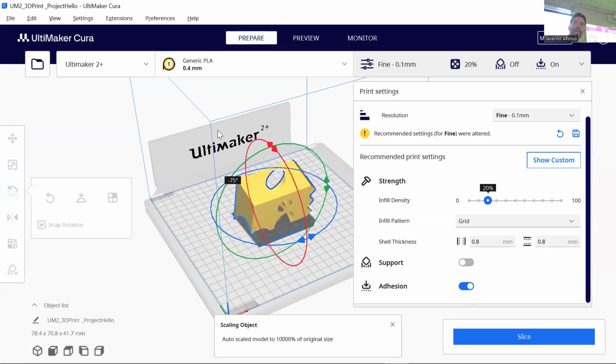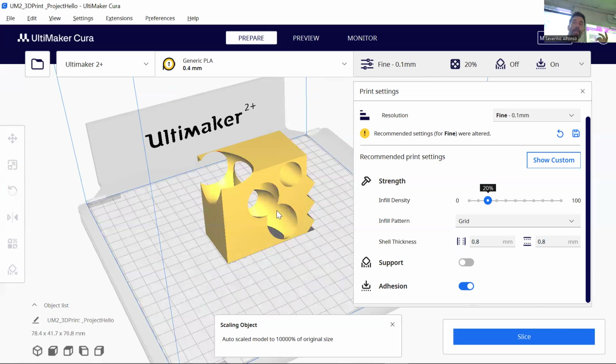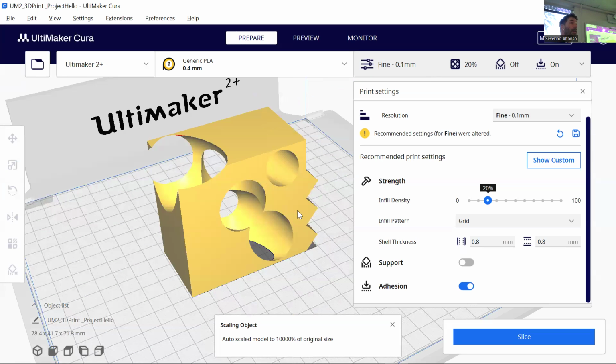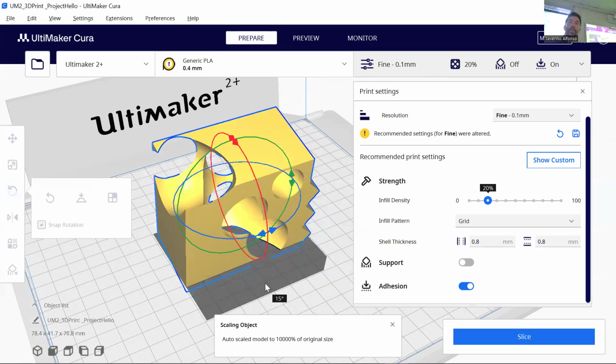This is very similar to how Rhino works. You can notice how it tells you the numbers. It's 90 degrees, and it allocates itself in the middle automatically. So it might be that your model is easier to 3D print like this. There's less cantilever. The main question is thinking about how can I avoid cantilevers as much as possible. How can I have a strong, massive base and less material above, more material in the bottom, less cantilever. So start rotating those and see what options are ideal.